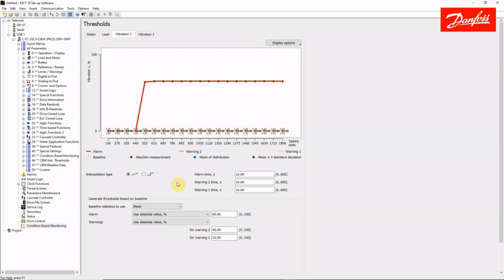Finally, we're going to look at the vibration tab or tabs. For the sake of our demonstration, we've only configured one analog input to accept an input from a vibration sensor. If you recall, we set that up as a 0 to 10G transducer, meaning that vibration levels of 10G would be reflected as the high end of what's coming in, whether it's 4 to 20 milliamps or 0 to 10 volts. More than likely, it will be a 4 to 20 milliamp signal, but you can't say that definitively. You can go either way.